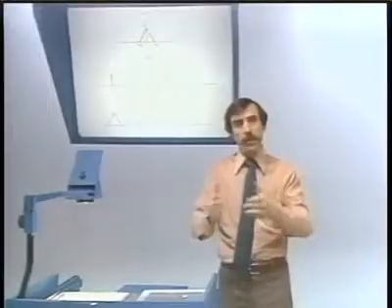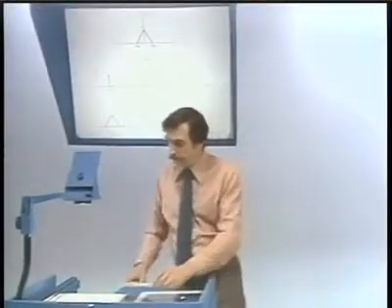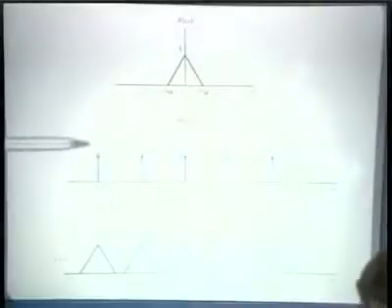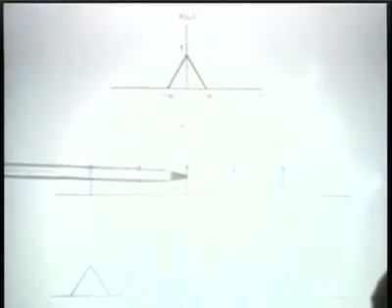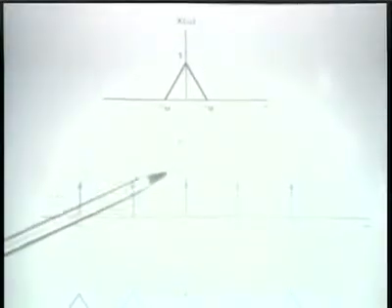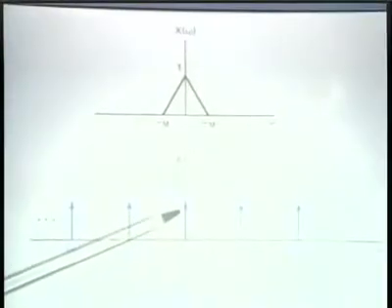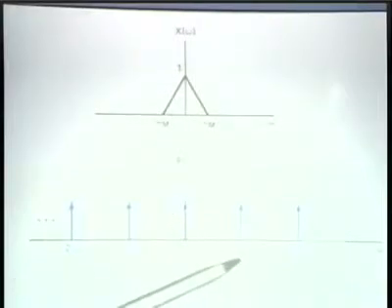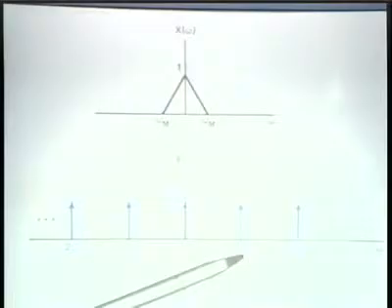In other words, the modulating signal is an impulse train. And so as we look at the spectrum of the modulating signal, that is then an impulse train in the frequency domain. The height is proportional to the frequency of the impulse train, and omega sub s now denotes the frequency of the impulse train.